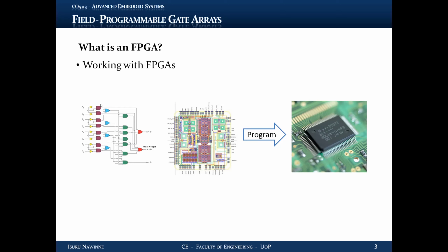So you buy the chip, then you have your logic circuit design, the gate level design, and you have to synthesize it, not onto a transistor level design this time, because you're not going to take the design to a foundry and ask them to etch that on silicon, right? You are going to put that onto an FPGA, which is already there, wired, packaged and soldered onto a circuit board. So you already have it.